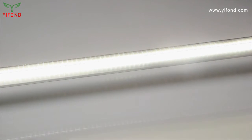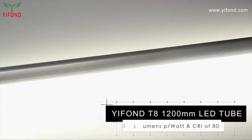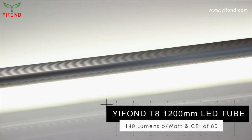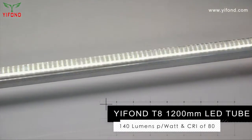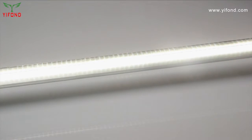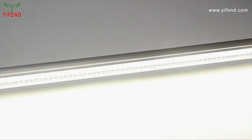This T10 range provides a highly efficient light output. They can produce up to 140 lumens per watt with a colour rendering index, often referred to as CRI, of 80 to comply with latest building regulations, and are available with a CRI of greater than 90 for special requirements on a made-to-order basis.